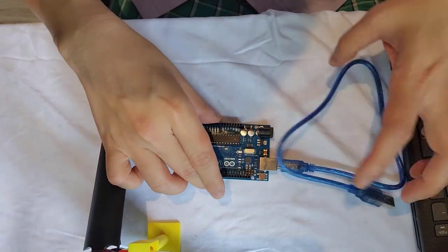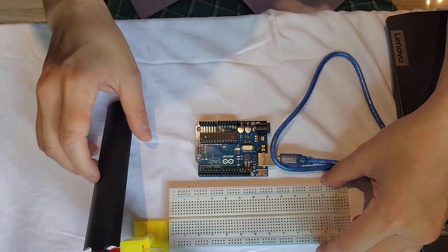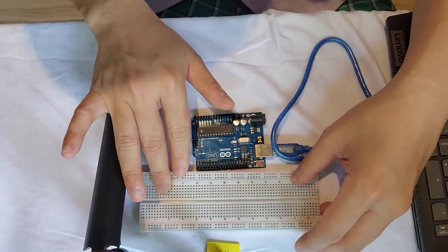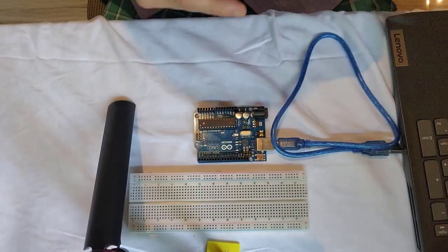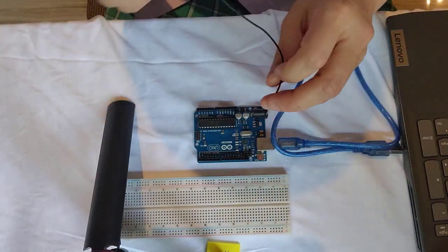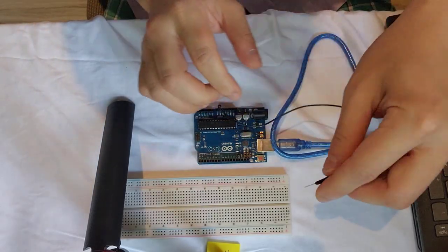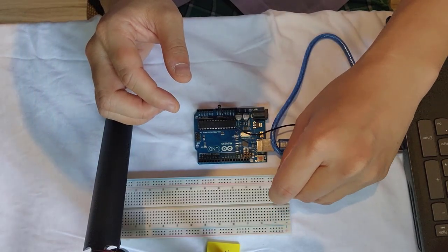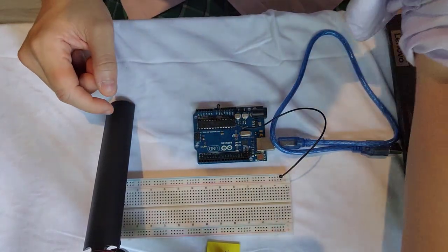We're going to get our Arduino here, our breadboard, right, and let's just hope that this all fits. Okay, and let's put this over here. Right, okay, so first we're gonna be hooking up a ground wire over here, GND on your Arduino, and then you're gonna be hooking it to one of these minus signs. So we're gonna be hooking that to the minus sign of the breadboard. So what it does is the whole bottom rail is now ground.